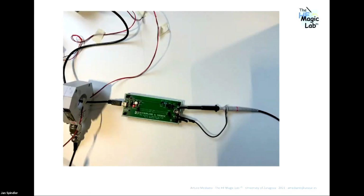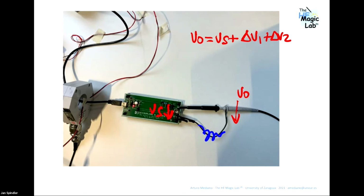So this is the signal we want to measure, VS. This is the signal you send to the oscilloscope, VO. And you have two effects. VO is equal to VS plus two additional voltages. One of the voltages is created by this inductance, which is around 100 nanohenries.